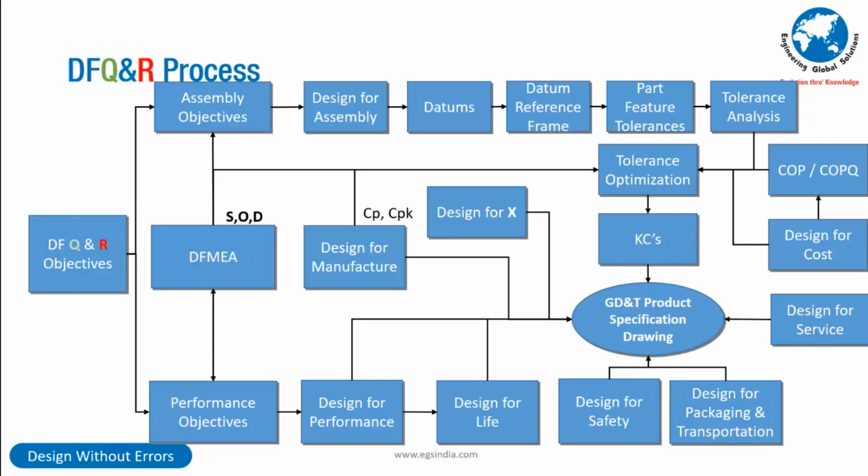Writing a small macro, driving it every time you build the final model before releasing it, it will tell you exactly where to put the counter mass, what should be the value of that mass, and then you do a sensitivity calculation based on your tolerances, and then you will be in a position to say what will be the level of vibrations that you will have on the bearings because of using this tool holder. This is an example which I thought I will share with you. This is more than two decades old.